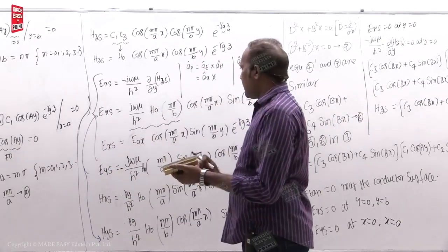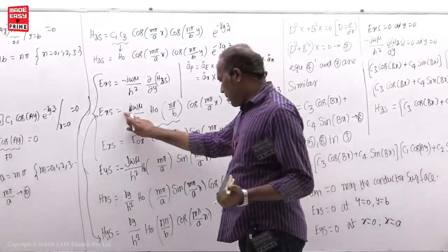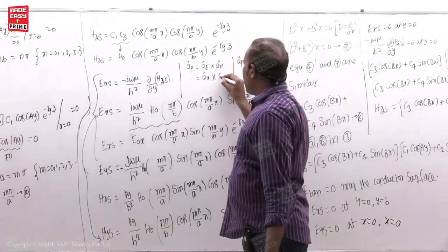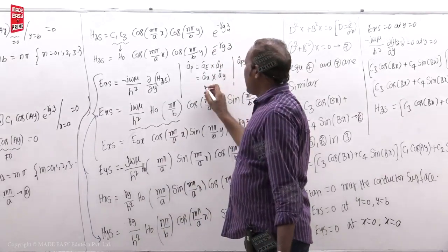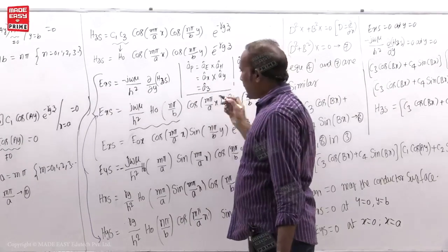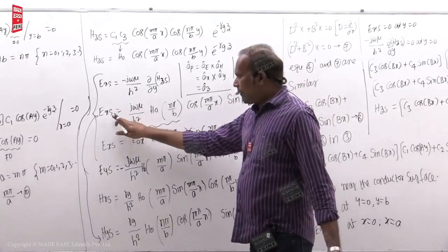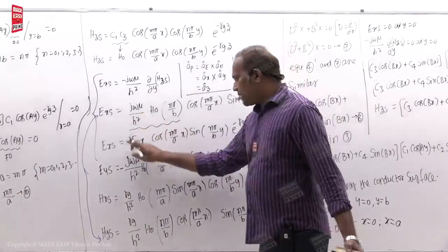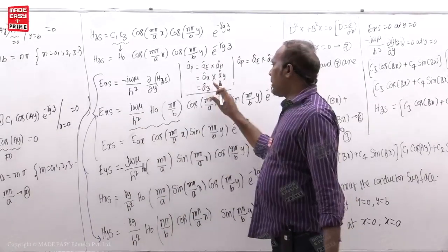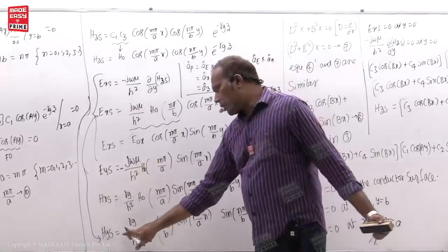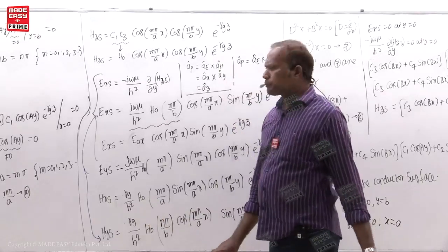So this has a positive sign, definitely this also should have a positive sign, so that here ay cap, then ax cross ay is equal to az, so power flow is in the az direction, correct. So this also has electric field x component and magnetic field y component, both with the same sign, so that they carry the power in the z direction. For example, if this has a minus sign, that also should have a minus sign there, definitely.